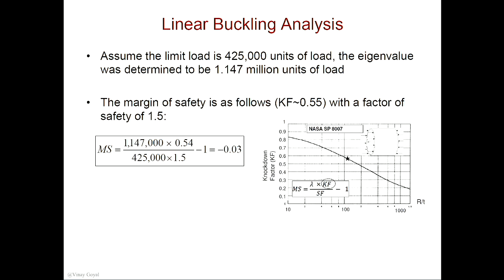But what we're saying now is, say I don't have a handbook for my particular situation. What can I do? What I can do now is run a nonlinear analysis and include the imperfection in my model. If I know the imperfection, even better, I can use the measurements from the hardware and put them into my model, and run the analysis nonlinearly. That's one way. Another way is that I could include the imperfections created by these mode shapes. So the mode shapes have a preconceived shape, right? I'll use those shapes on purpose in my analysis, and I'm going to say, okay, my model has those imperfections.